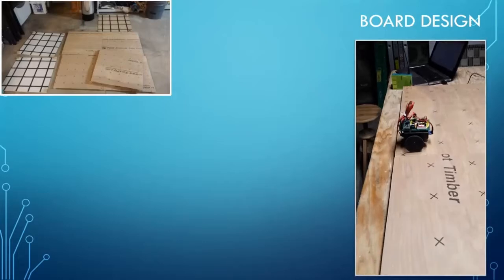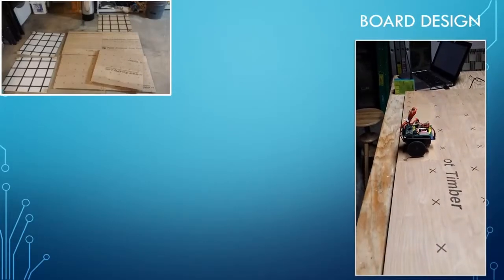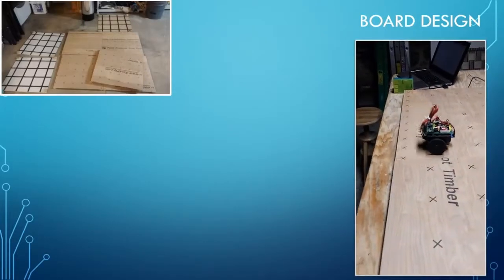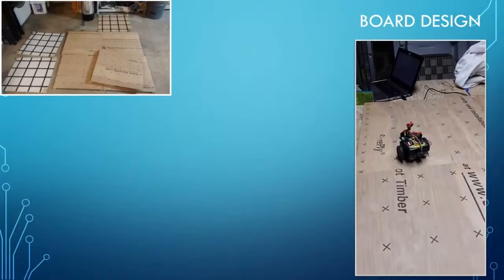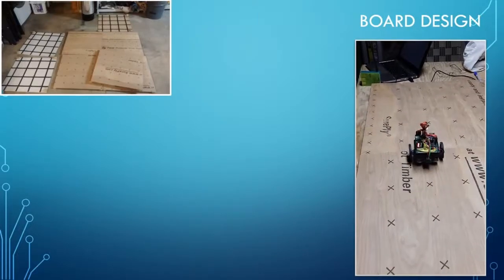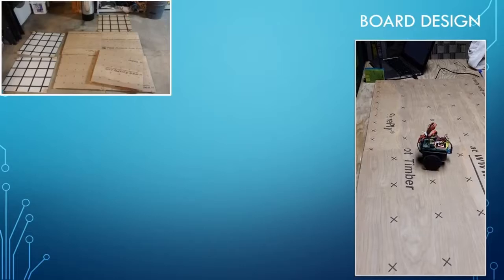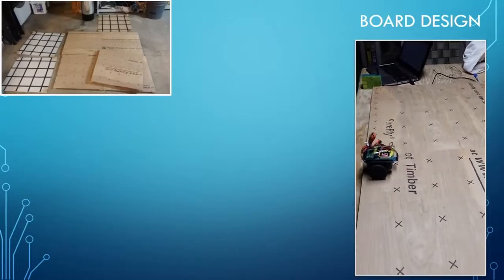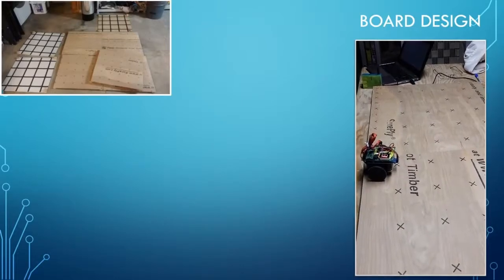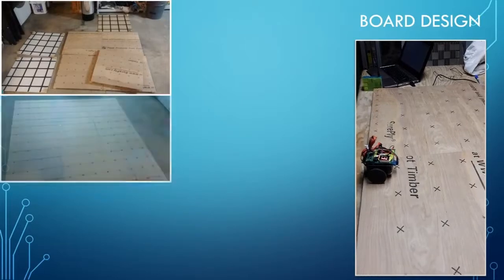And then the robot, in this video, you can see it navigating by following the magnetic tape. And as you can see it moving, you'll see that it wobbles back and forth a bit. And as it's wobbling back and forth, that's the magnetic compass, the magnetometer, trying to keep itself on that magnetic field line. And it does a pretty good job for a first attempt.